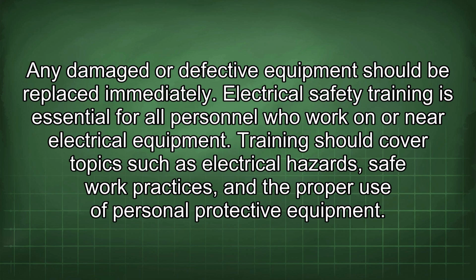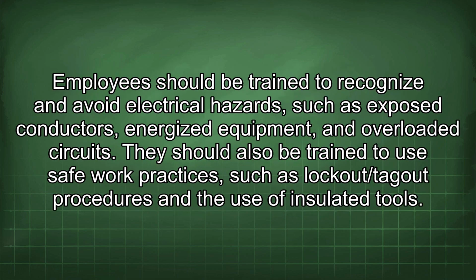Electrical safety training is essential for all personnel who work on or near electrical equipment. Training should cover topics such as electrical hazards, safe work practices, and the proper use of personal protective equipment. Employees should be trained to recognize and avoid electrical hazards such as exposed conductors, energized equipment, and overloaded circuits. They should also be trained to use safe work practices such as lockout/tagout procedures and the use of insulated tools.